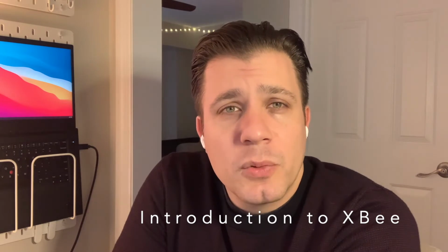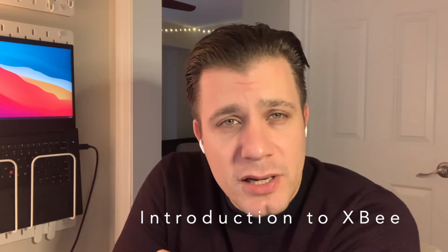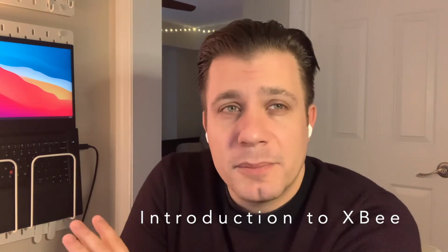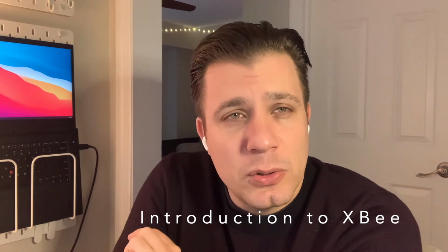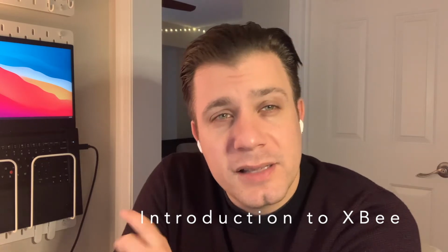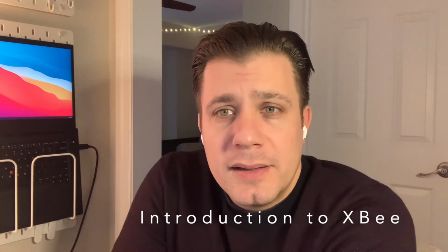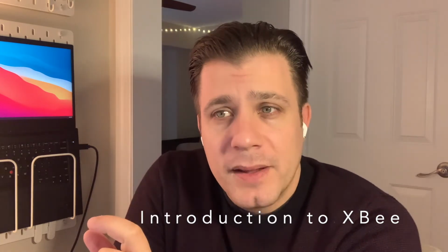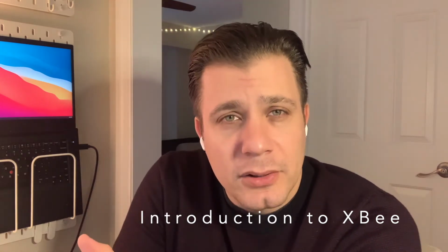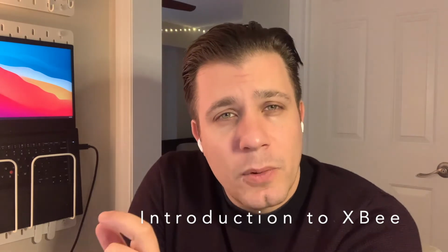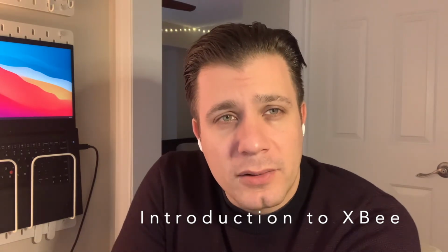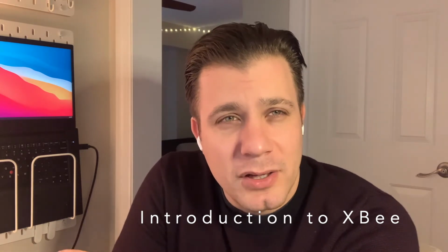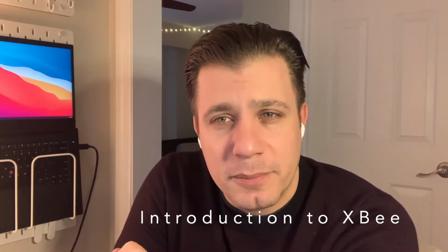Now, we are going to work predominantly with the Digi-manufactured XBee, ZigBee-based, XBee Series 2 module, both the standard and the Pro version. Now, Digi also makes XBee modules under that same name that employ Wi-Fi, cellular, and Bluetooth connections. So when you're buying radios, you want to make sure that you're not only looking for the XBee name, but you're also looking for the ZB. They often abbreviate the ZB, ZigBee type.